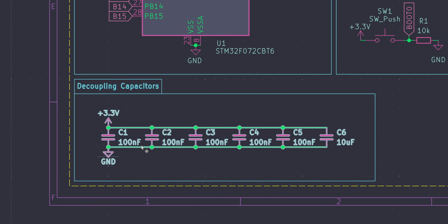Technically, I think you need 7 according to the data sheet for the STM32, but I'm using this one here. It does work. It uses minimal parts and is a lot simpler to understand. But basically, we just have a bunch of capacitors here. One end is connecting to the 3v3 up top, and then down here is just going to ground. So pretty easy to understand there.